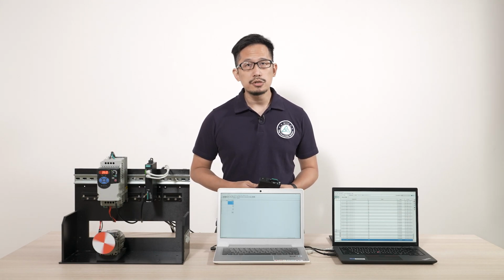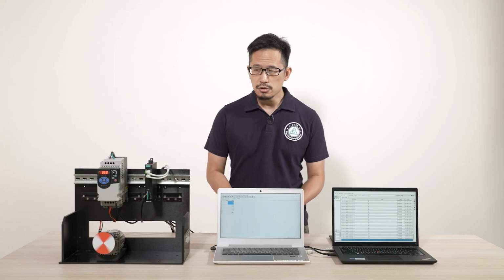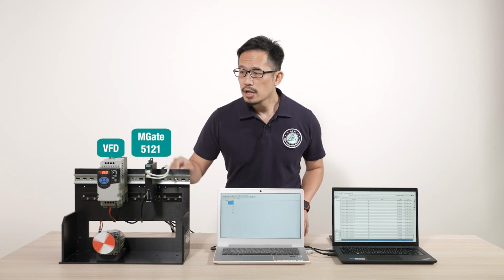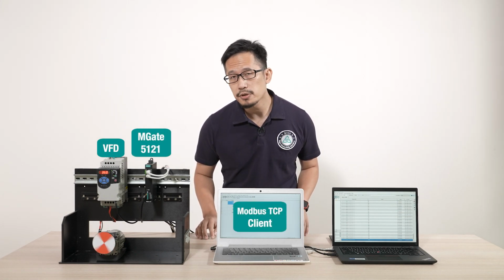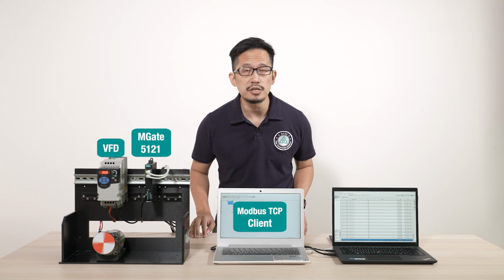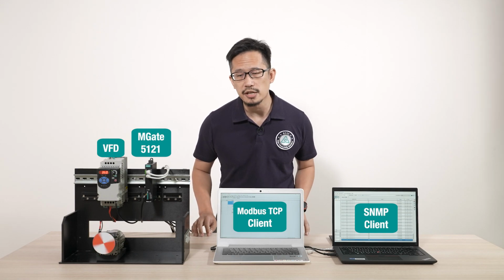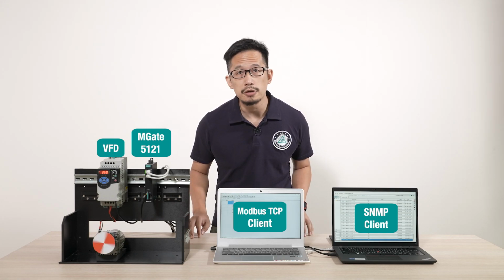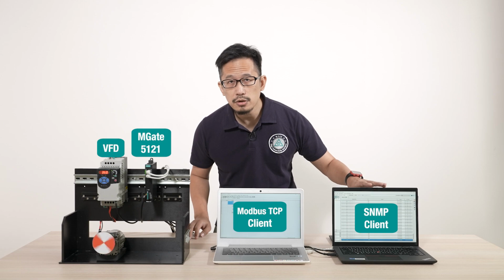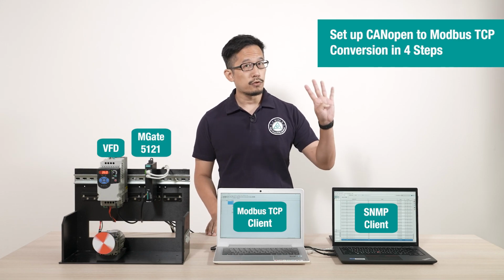So for this demo, I'm going to show you how easy it is to add a CANopen device to a Modbus TCP network. Over here, we have a VFD that uses CANopen, and we connected it to our MGate. Our MGate is connected to a laptop that's running a Modbus TCP simulator to act as our SCADA. Now, the MGate can also simultaneously convert CANopen data to SNMP, allowing IT systems to also monitor device status without any additional converters or hardware. So our MGate is also going to send converted CANopen data to this laptop over here, which is running an SNMP MIB browser. And I'm going to show you how you can do all of this in just 4 steps.